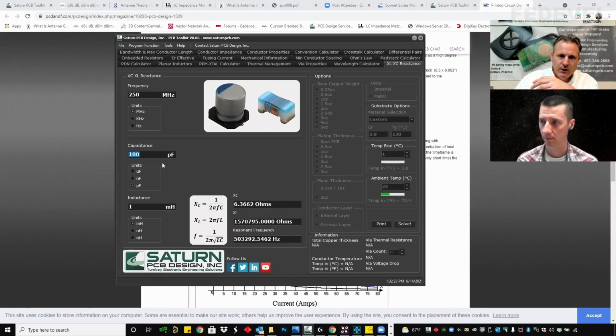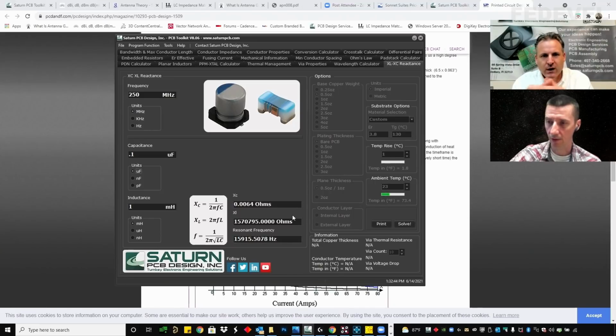We changed those to 0.1 microfarads, and you can see that I'm way down now. So the capacitor isn't affecting the RF transmission as much. It's simply there to block DC between one stage and the next, and not to interfere with the RF signal itself. So the 100 pico, because also the resonant frequency is very low. That's the reason. Yes, correct.